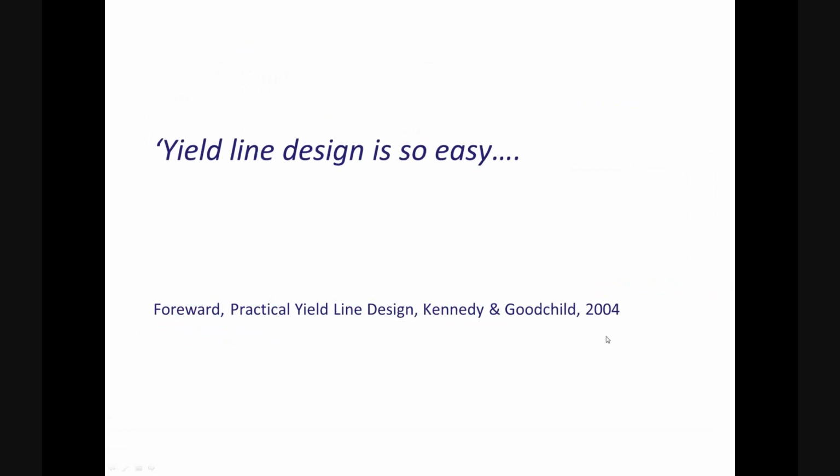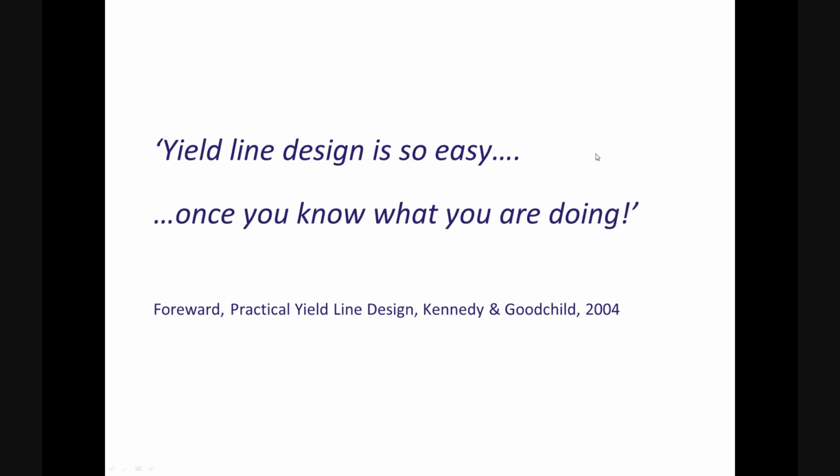And what they did at that time was they produced a design guide, and in the foreword it says, Yieldline design is so easy once you know what you're doing. And the big issue is that not enough engineers have felt confident to use the Yieldline method as a hand method because of the concern that a critical failure mechanism is being missed.